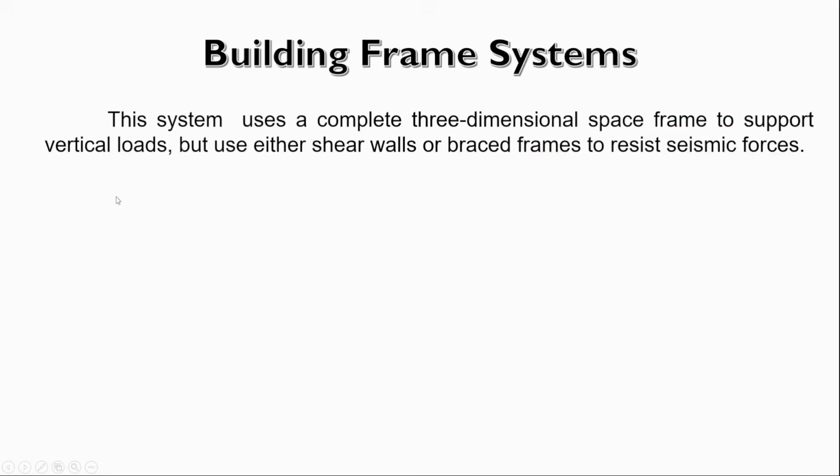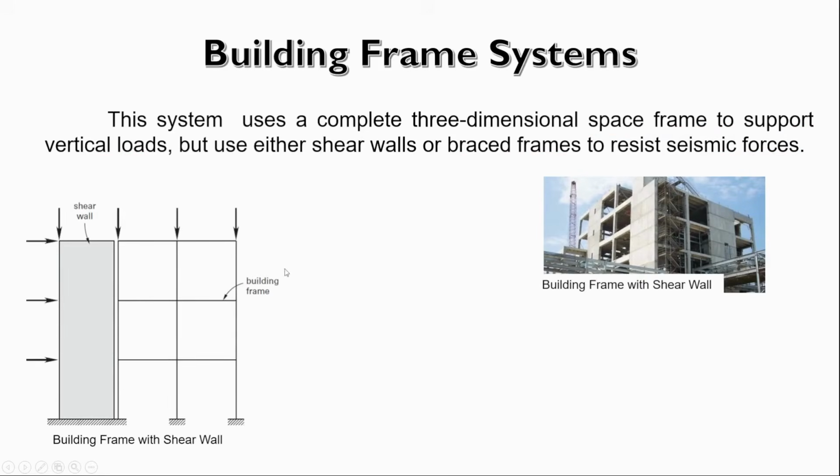So let's see some pictures. As you can see, the space frame resists the vertical loads, but the shear wall here resists the lateral load. So take note of which element resists the lateral load, or the earthquake load, and which element resists the vertical load.